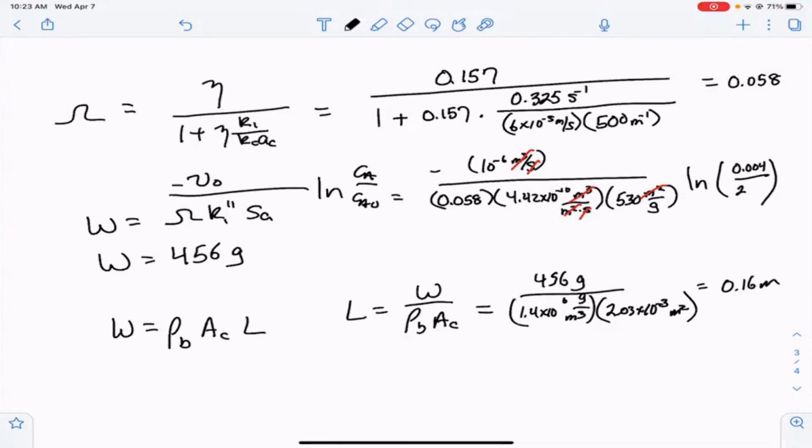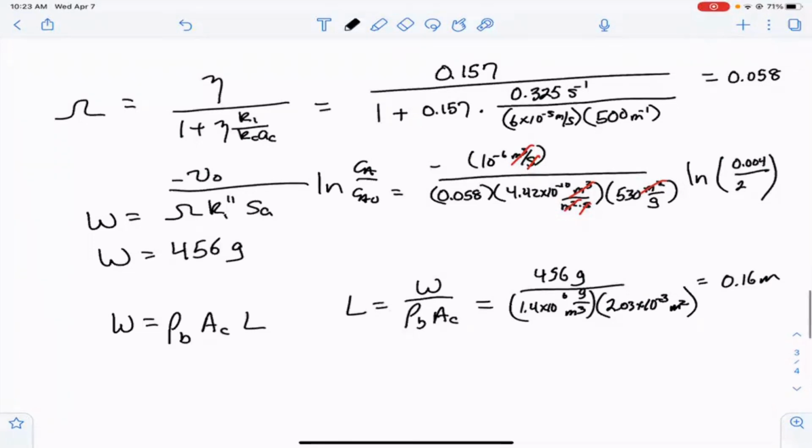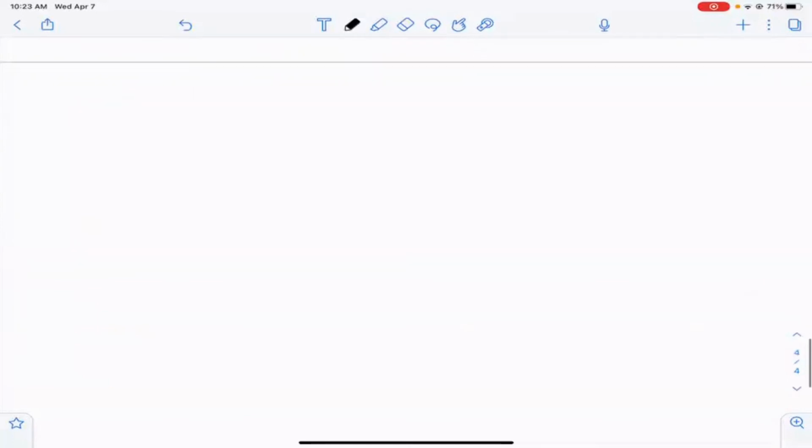All right, if not, so now that we have this, I really want to talk a little bit about what the values mean for the internal effectiveness factor and the overall effectiveness factor. One of the things that we would think about is that if the internal effectiveness factor is about 1, that means that you probably don't have any internal mass transport limitations, right?